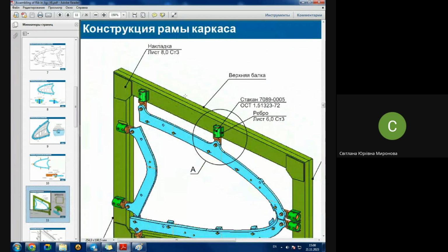What is the advantage? Very accurate and extremely quick. You don't need to drill holes in this case. You don't need to polish surfaces, and so on. You just attach it in the proper place. What is the proper place for this fork? It's another story. Actually, we are not usually interested in the proper place for the fork. We are interested in the proper place of these contours, of locators and their contours.